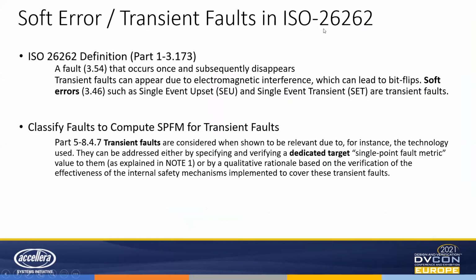I just want to highlight that ISO 26262 actually recommends using soft error analysis, or transient faults, to do further functional safety analysis. And these faults are called transient faults, and you should have a dedicated SPFM target for transient faults as well.